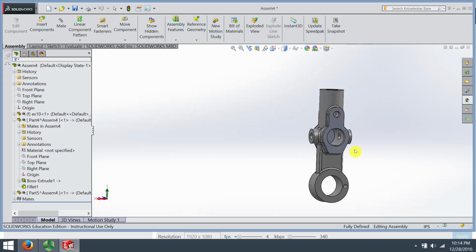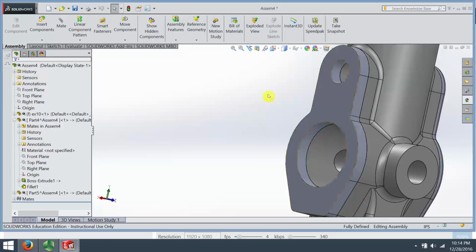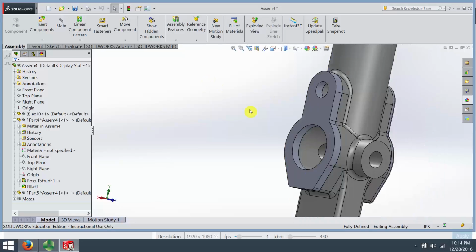So now we've built 3 components in just no time at all. And this last one especially, to me, it's just awesome that it works this way. Is I know that this hole diameter is a match for that hole diameter, and that this one is a match for this guy. Because I derived them, I converted entities and brought it right from them. So that's a good reminder. Don't just draw a circle there. You're back to drawing your own individual component that way, and you're not deriving from any of the geometry that's already here. And to get the benefit out of this, that's what we want to do.